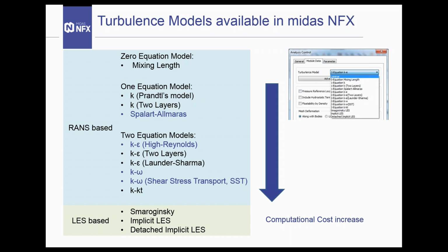As I said, the Spalart-Allmaras is very good for mildly complex external and internal flows. It is good for problems with flow around airfoils, wings, ships, for example, but performs very poorly for 3D flows. So it's not valid, for example, for flows with strong separation.